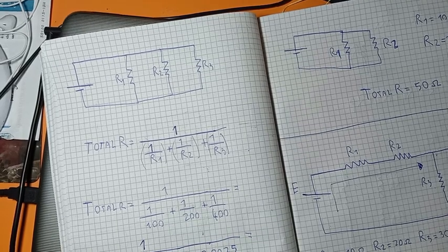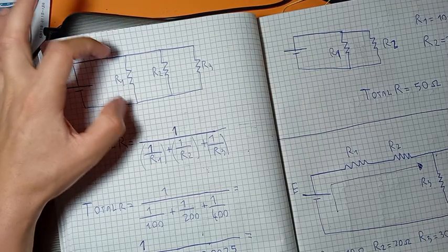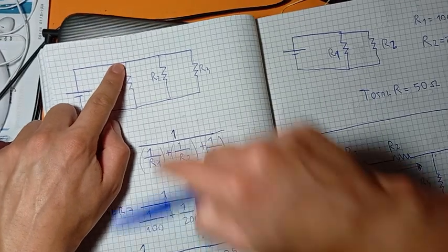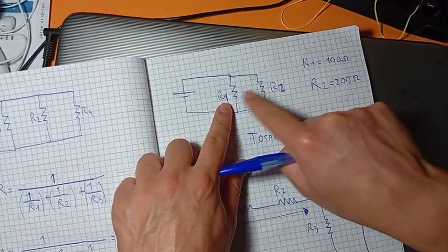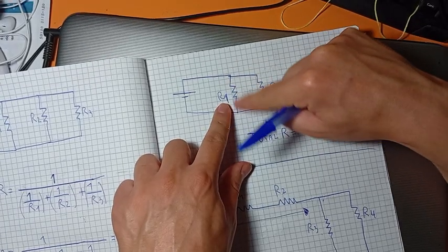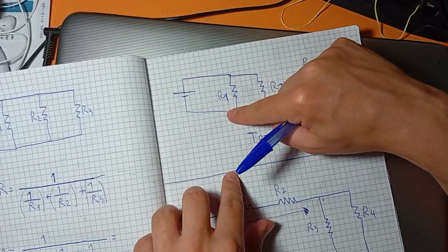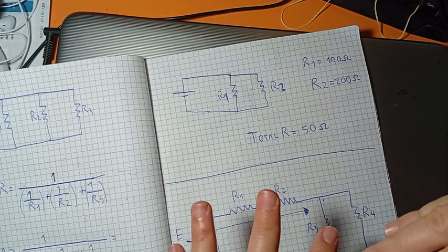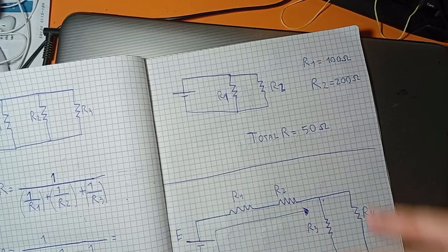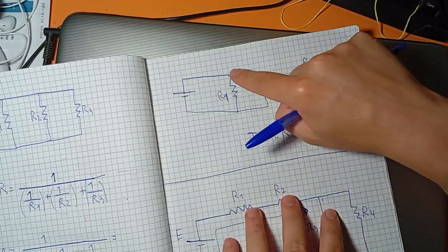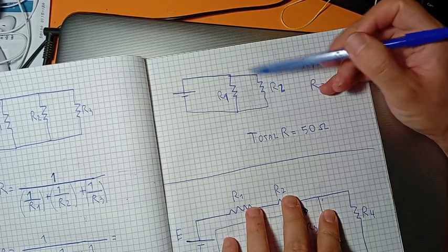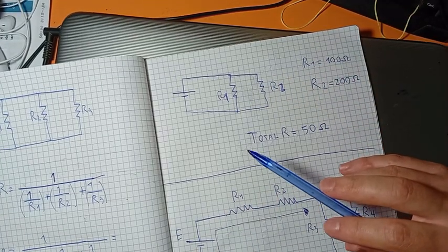Sounds like the meme. Okay. What is in parallel? This circuit begins with a single branch here, and this branch divides into other branches. So it's not the resistors who are in parallel with the other resistors, it's this branch who is in parallel with this other branch. Remember this. It's not the resistor who is in parallel with the other resistor, it's the branch who could be in parallel with another branch. This branch, in this case, is in parallel with this other branch, okay? So the branches are in parallel, not the resistors.